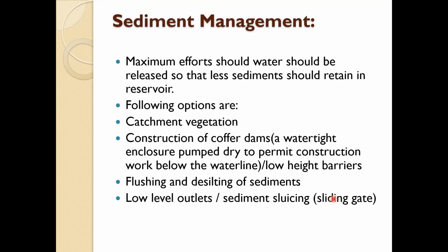In construction of check dams, as I have told you earlier, the sedimentation inflow can be controlled by building check dams across the river streams contributing the major sediment load. These are smaller dams and trap a large amount of coarser sediment. So it is effective, but they are quite expensive.